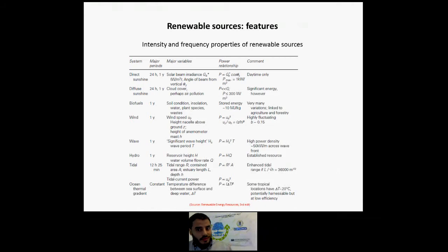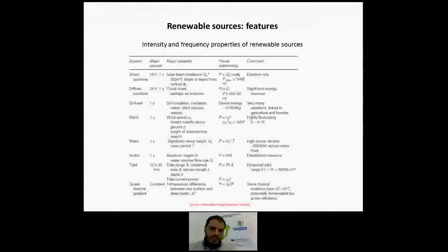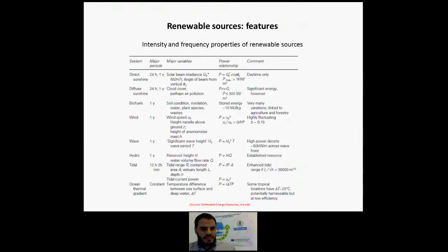The quality of nuclear, fossil or biomass fuel in a single stage thermal power station is moderate because only about 33% of the caloric value of the fuel is transformed into mechanical work, and about 67% is lost as heat to the environment. Well, if the fuel is used in a combined cycle power station, that is, a methane gas turbine stage followed by a steam turbine, the quality is increased to about 50%.